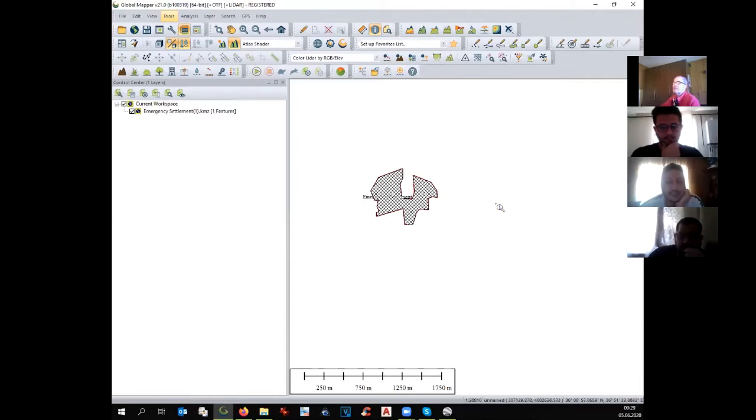Okay, so it's something that we can start from the Google Earth. In the Google Earth itself, you can adjust the units. Then you can transfer it to Global Mapper, and even in Global Mapper, you need to check if it is 84. Yeah, I remember it should be 84. 84 UTM 37 North. Okay, yeah.